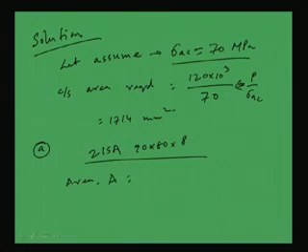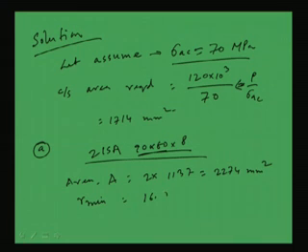Like say area, the total area will become 2 into the individual area, 1137 for this section ISA 90 by 60 by 8. So, this is coming 2274 millimeter square. Now, r minimum of the individual section is 16.9 mm, and the effective length as per the code provision is equal to the length between the intersections, that is 2.5 meter, that means 2500 millimeter.